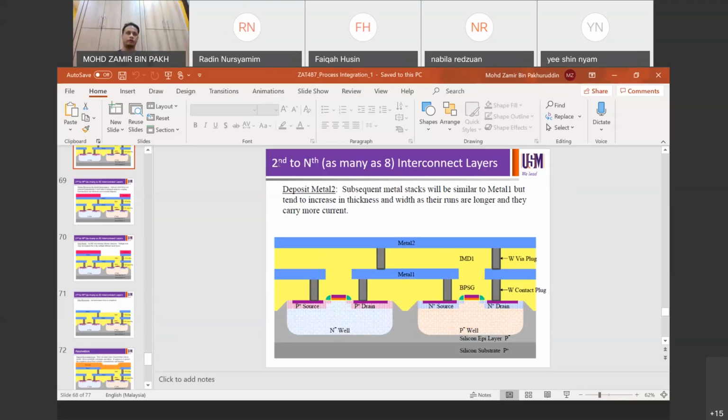If you talk about cadmium telluride solar cell, for example, then you're going to be overseeing process flow of ITO deposition, cadmium sulfide as the buffer layer, cadmium telluride as the absorber layer, and then a couple of metal layers at the back as the rear contact, and then the probing, the interconnect between your device to device on the glass.